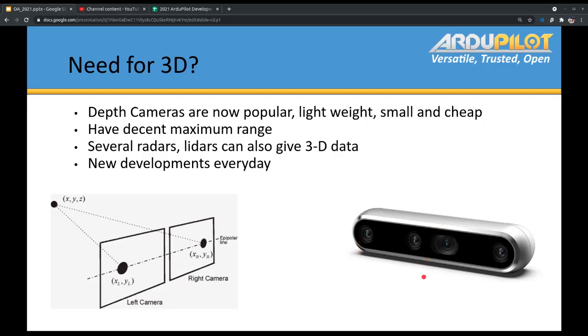Apart from that, we also have an incredible RGB camera in the center. So what we can do is run all those ML and AI algorithms that classify obstacles, and then you can figure out in camera coordinates the u comma v, which is the coordinates of, say, a human or a toddler walking across. And then you can figure out the XYZ, the actual physical body frame coordinates of that obstacle. So that's why these cameras are fantastic, and they are being made better every day.